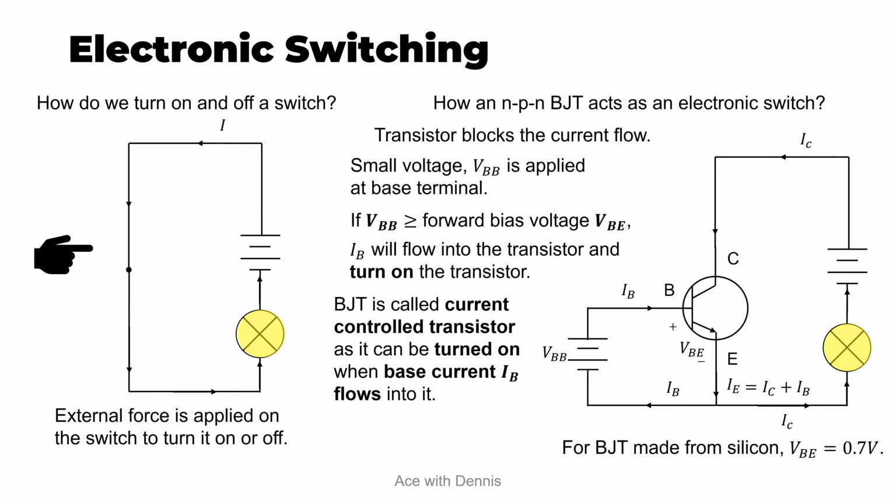After understanding how electronic switching works, let's discuss the light-sensitive switch. A light-sensitive switch circuit consists of two components. The first component is the potential divider component, which is made up of R1, a fixed resistor, and R2, a light-dependent resistor, LDR. The second component of the circuit is the electronic switching.